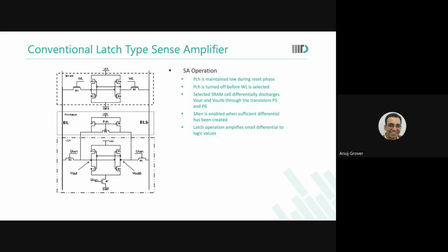And even though the structure is very similar to the standard 6T cell, the design is done very, very differently. In a standard 6T cell, the layout that we saw, you realize how dense it was, with so many rule violations, and sharing across cell boundaries and so on. Now, this is a sense amplifier. It's an analog circuit. The memory cell is also an analog circuit, but this is where the entire speed, power, everything is going to be determined. So over here, you design the sense amplifier very, very carefully. You make a common centroid layout for a sense amplifier.